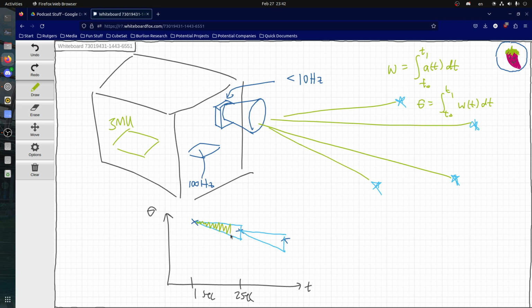Because IMUs usually are filled with noise and bias, right? You've heard of gyro drift, where the gyro just slowly drifts away. So what we do is we say, okay, we're definitely in this range, and this accuracy is usually better than just using the IMU, because if you just use the IMU, this thing will just continue drifting away. We'll get to this later, but if you use a filter, then you can bound this even more on each one.